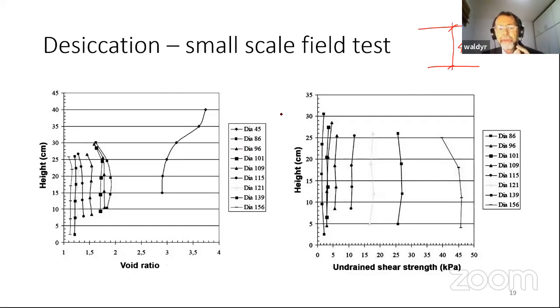So let me talk about the whole story here. Until day 45, the material was just discharged on that area, allowed to sedimentate and then consolidate. At day 45, the material had just consolidated when he did this sampling. So you see high void ratios.